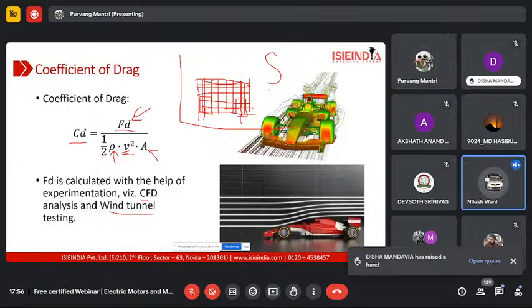Sir, sorry to interrupt. Yeah, but we can do it in CATIA as well. You can do it in CATIA as well. We can project it on the surface. Exactly. And if we trim out the outer area, then we directly get the area by the measure tool. So we're not doing it the hard way, that's like using your smart brains. That is the best method.